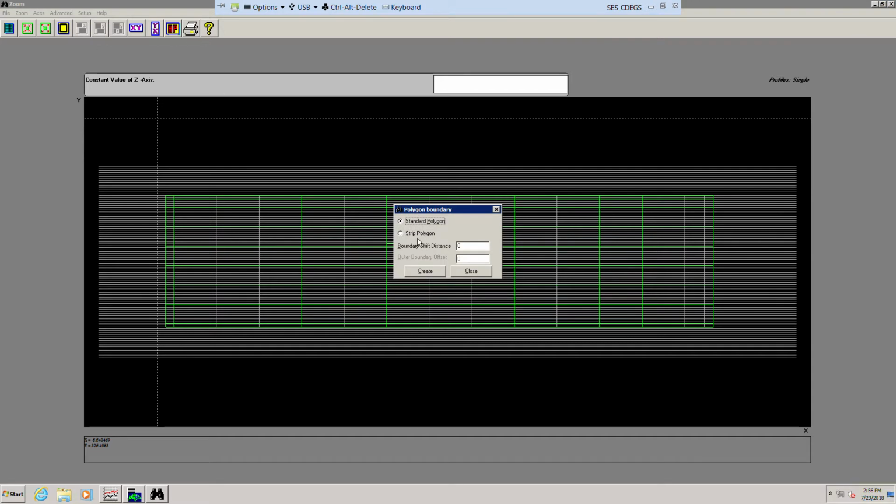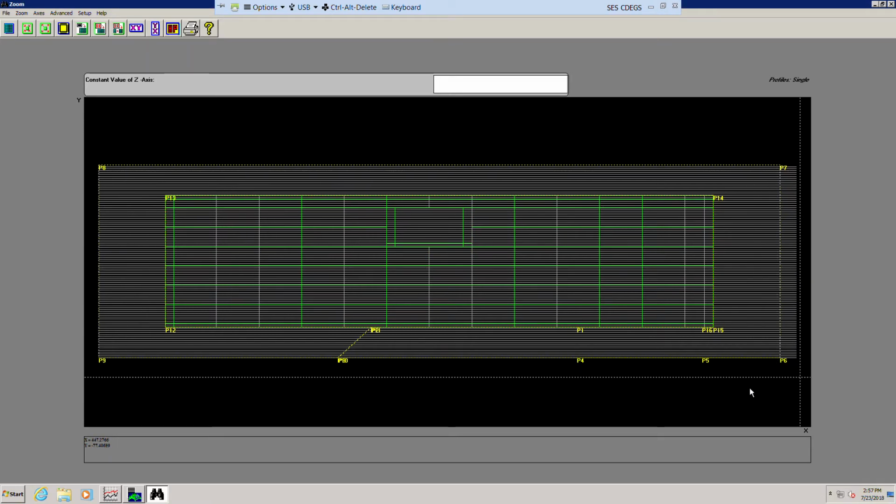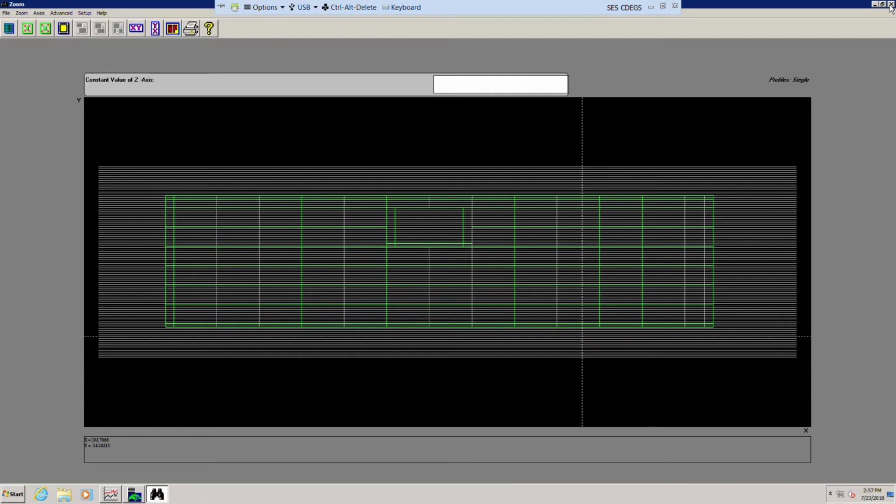and then we have this inner offset at 0. That's going to be, so 0 is 3 feet outside the fence, and in order for us to go 50 feet outside the fence to check, our outer boundary is going to be set to 47, because our 0 here is 3 feet outside the fence. So 47 would give us 50 feet outside the fence. So we set this as 47, and we say create, and so it gives us 50 feet outside the fence to be examined. And then we click back up here again, send zoom points, and we close this out.